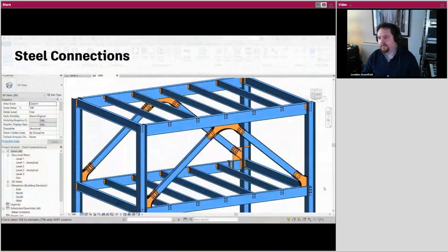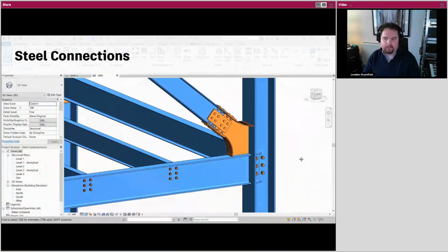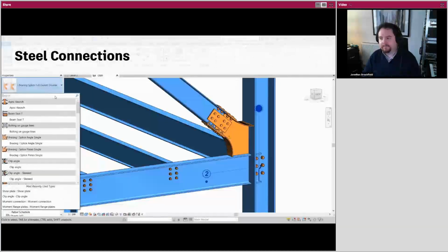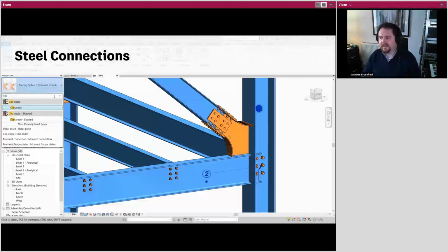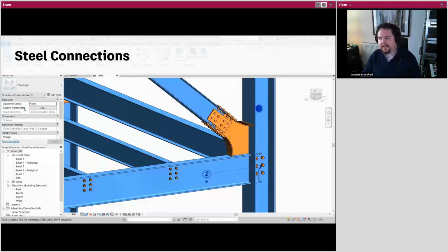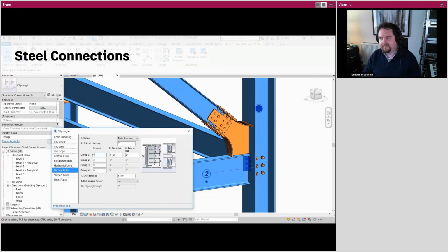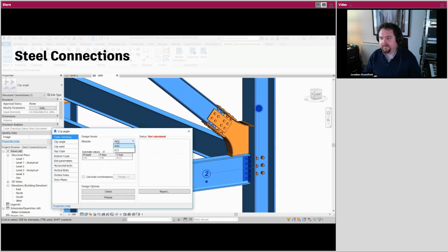Revit provides access to a variety of parametric steel connections, enabling connections to be modelled with higher level of detail. This includes a built-in steel connection design engine based on US and European codes, which allows structural engineers to verify the connections in Revit before the model is sent to the steel detailer for final detailing. The code check report includes references to highlight the chapters to which the verification belongs, according to the American Institute of Steel Construction, or AISC standards.